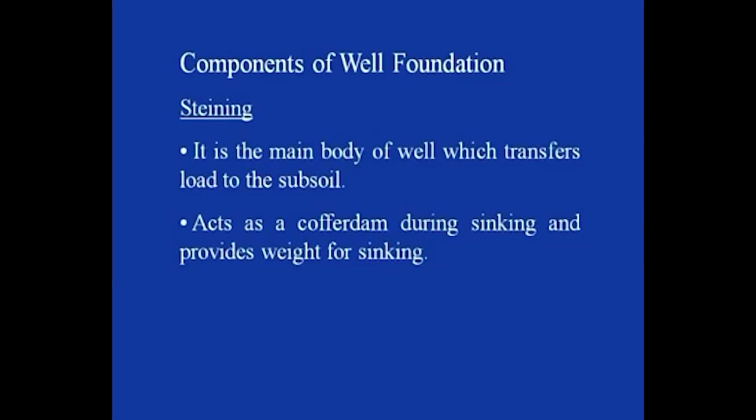The second component, the most important one in the case of the well foundation, is the well steining. It comprises the main body of the well, which transfers the load to the subsoil. This acts as a cofferdam during sinking and provides the necessary weight for sinking.